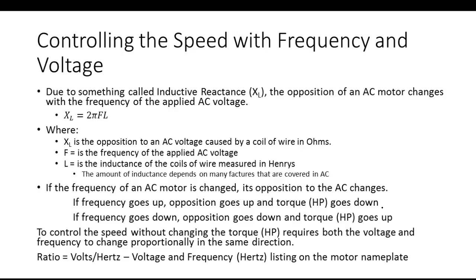You got a big horsepower motor and you start them suckers across the line. Well, yeah, 6 to 8 times its full run torque. So you got a 100 horsepower motor, you turn that sucker loose starting it up, that sucker could generate 600-700 horsepower of power. What could it do? It'd tear some stuff up, yeah. So we used to deliberately lower the voltage while the thing started. We call them reduced voltage starters. So you run it through resistors or you run it through inductors, and then when the motor starts running, you switch it over when it's already running. So reduced voltage starters. A variable speed drive will do that for you.